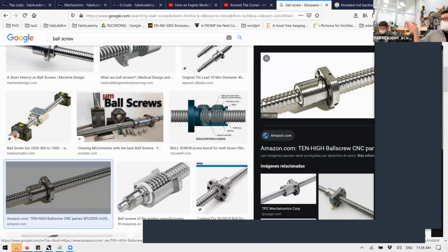And for example, 3D printers are doing this because the cost of one axis of this is the same price as two 3D printers. So they use a threaded rod with a normal nut, and the first upgrade that you can make to these machines is an anti-backlash nut. Just change the type of nut that you use. If you have money, choose one of the ball bearings. Say that, for example, good FDM 3D printers in the 5 to 10K range, one of the differences will be that the axes are ball bearings.